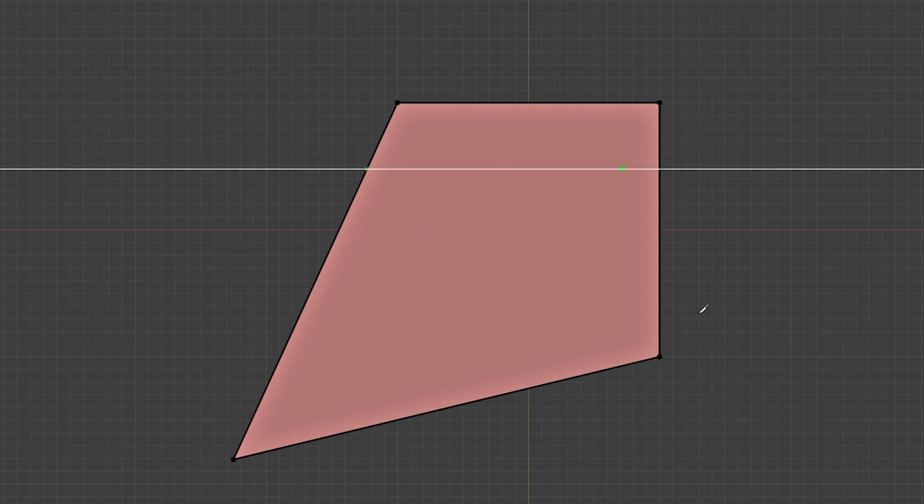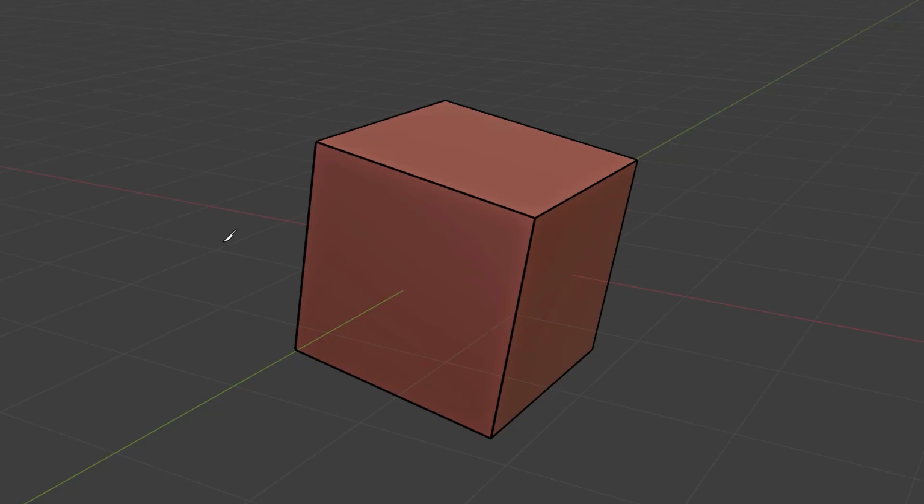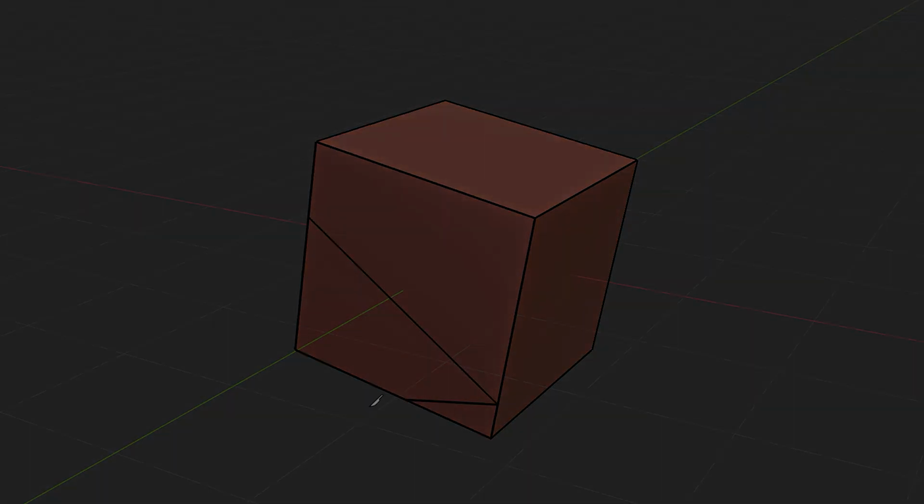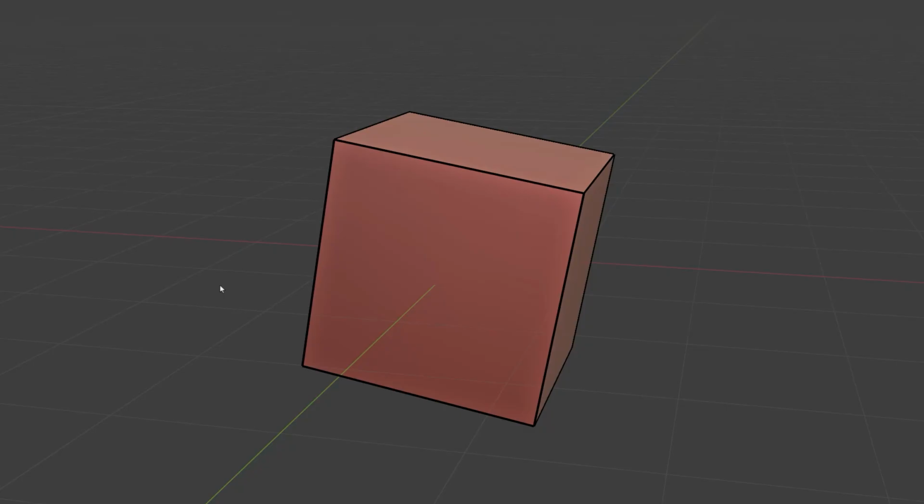If we are making cuts that require exact sizes or angles between edges, then we can press the S key. This displays the lengths of all the potential new edges, as well as their intersection angles. One last key we can make use of when cutting is the Control key.